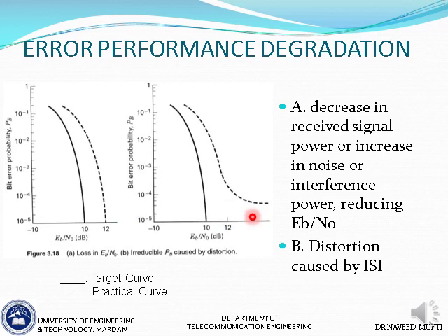So what's the bottom line? That increasing SNR does not solve the problems related to ISI. So they have to be dealt with in a different manner. So what do we do? So the cure to that is a technique called equalization, and that's what we have studied, that whenever we have distortion, we go to equalization. So since the distortion effects of ISI are caused by filtering in the transmitter and the channel, equalization can be considered as a process that reverses such filtering effects. So that's the idea.